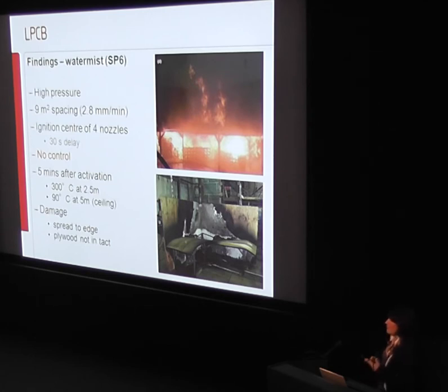You could argue there was some level of control because you actually got cooling in the space. So it was better than the free burn arrangement. The other thing I should mention, because I know people here are interested in sprinkler skipping: with the high pressure nozzles, we were only getting one of the nozzles operating.